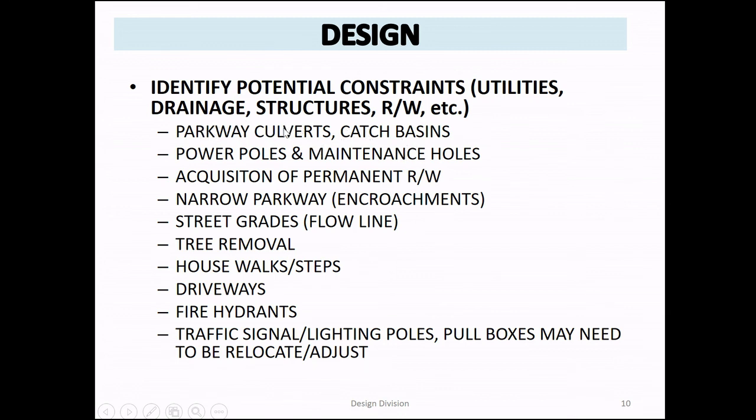We just had a project with Mark where we had to adjust the flow line a little bit just to make sure that we missed the parkway culvert. Because if you encounter one of these, there's no way you can meet your new construction 7.5% running slope.